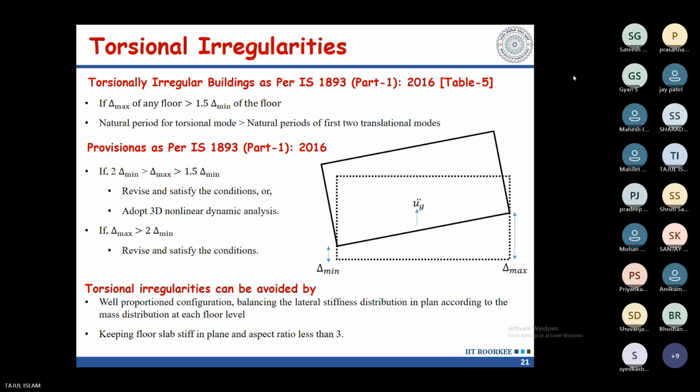There you input this VS30 and magnitude, and they will ask some other parameters also, but whatever you know, you provide. At least the minimum parameters will be VS30 and magnitude. Then the website will suggest a set of ground motion data, which you can take and use for your structural analysis. So you have two options.